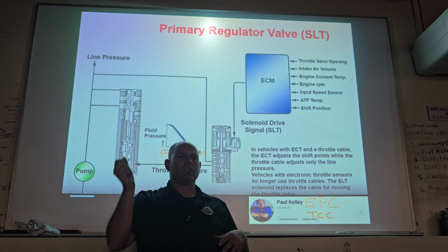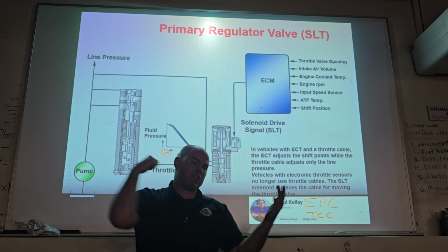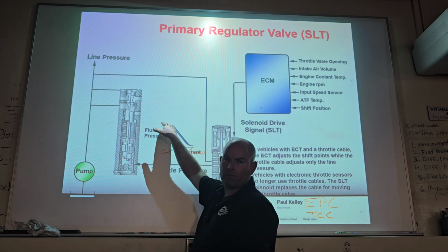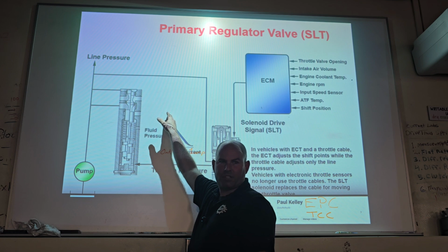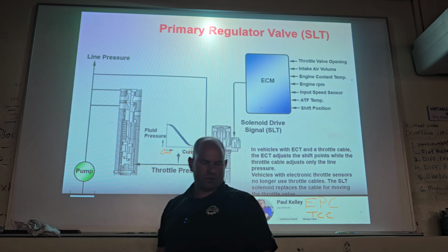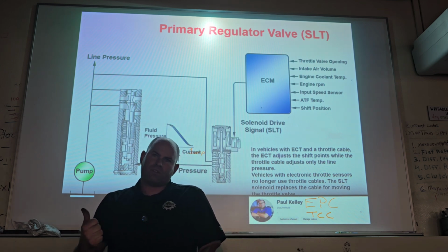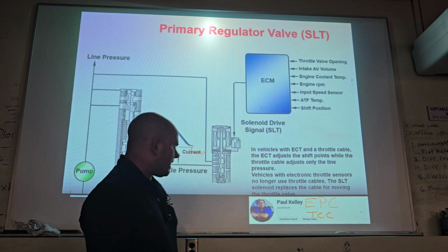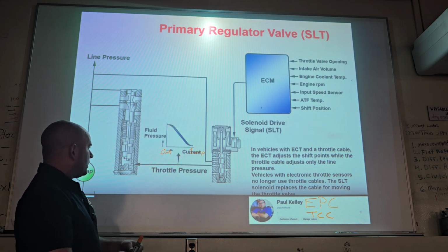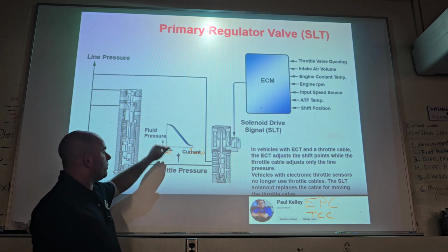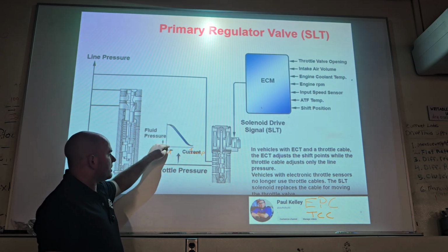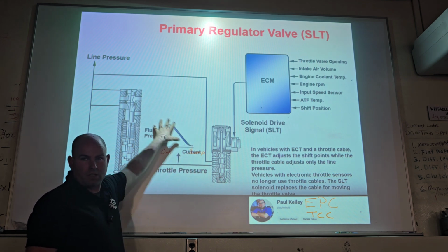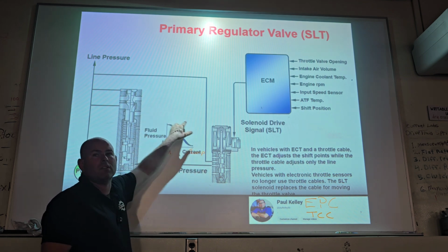And so that's why if you disconnect the transmission and put it in gear, it's going to slam in gear, bam! Because it's got no amps going through SLT, and that means high line pressure. And it's probably going to default to fourth gear and forward, but reverse is underdrive anyway. Wham, snaps your neck, okay? So if you were to see anything related to the ASE about low milliamps of flow, that's going to be high line pressure. If it's got high amps, that's commanding lower line pressure, okay? That stuff is on the ASE.